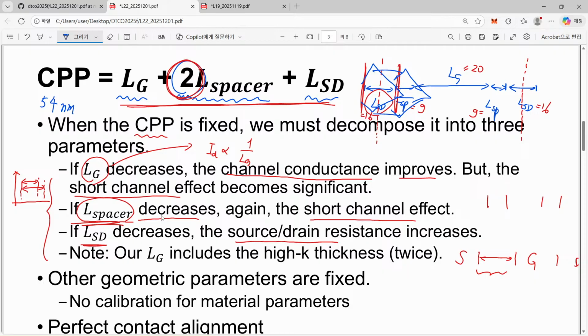But on top of it, we make salicide, and on top of that salicide we also introduce a via, so the connection from metal 0 to this internal device source drain.